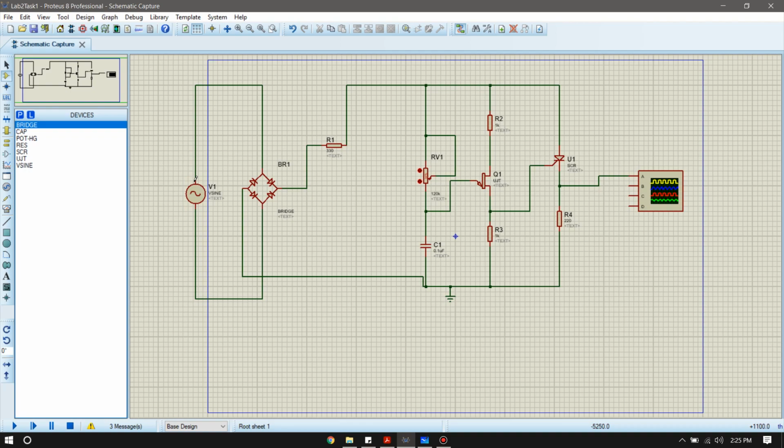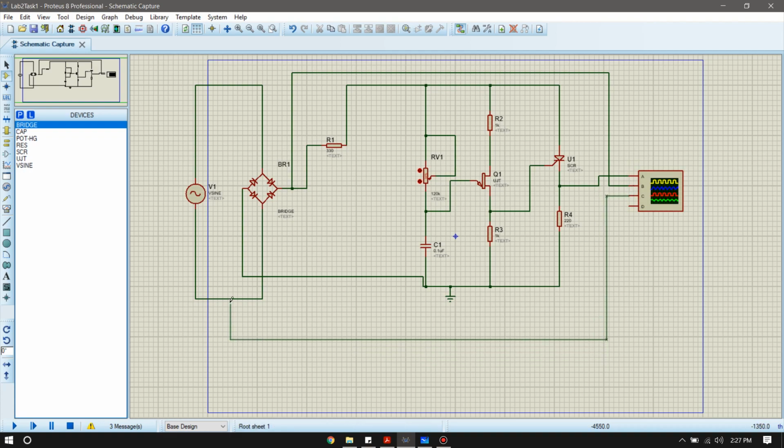We're sort of using a loophole to make a full wave rectifier, but in this case we can see how our SCR triggers for both the positive and negative half cycles. Again, terminal A of the oscilloscope will observe the output of our rectifier, and let's put terminal B at the output of our bridge. That's the positive after we have rectified the initial voltage source, and let's put C to our original voltage source so we can see the difference.